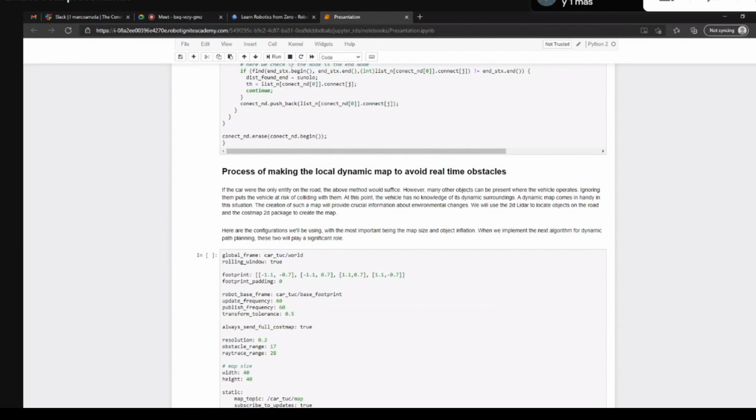In order to achieve this, we're going to use the 2D LiDAR, and we're going to map the 2D LiDAR data into a 2D map. Yet again, it's somewhat the same procedure that we did with the camera, but this time it's going to be easier. And this is thanks to the ROS community for providing us a package that does this exact operation.